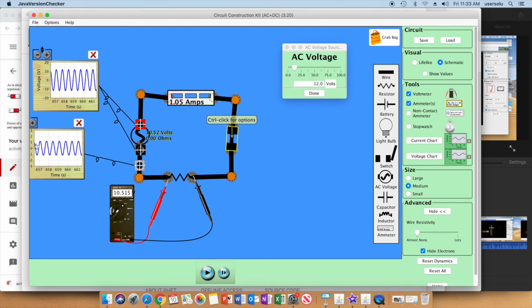I come down to this one, it's hard again to see because the markings are not telling me, but believe me, it's at plus 1.05 amp. Now again, I'm just going to arbitrarily let it run and then let it stop. Now I'm at negative 9.24 volts, I'm at negative 0.92 amps. So if I come over to my origin, I'm right at negative 9.2 volts. I come to this, I'm at negative 0.92 amps.